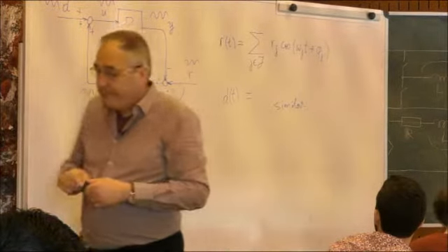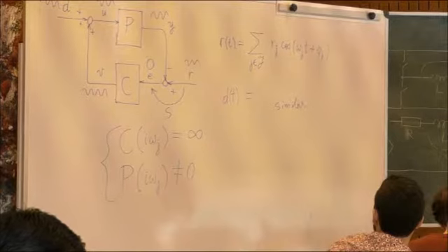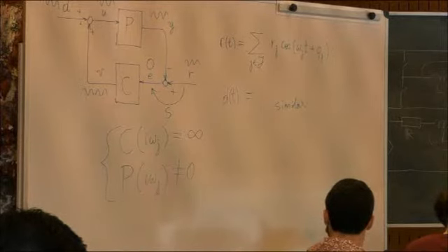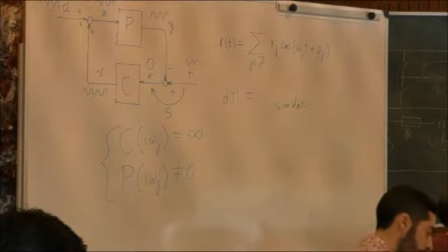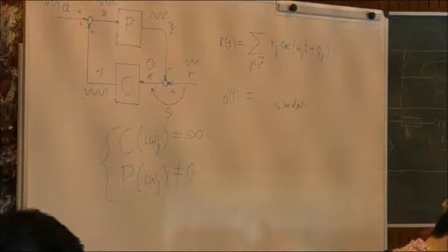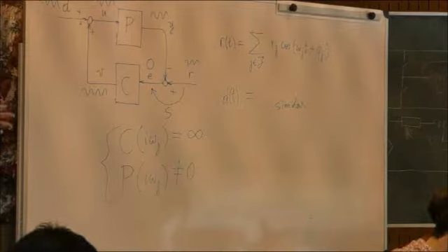So that means that the controller on its own is able to produce the same signals as the reference and the disturbance. Yes? The controller, while receiving nothing, zero input, is able to produce permanently the correct signal which will keep the system at 0 error, which means a superposition of the same sinusoids like R and D. So that means that the controller is an internal model. It is a model of these